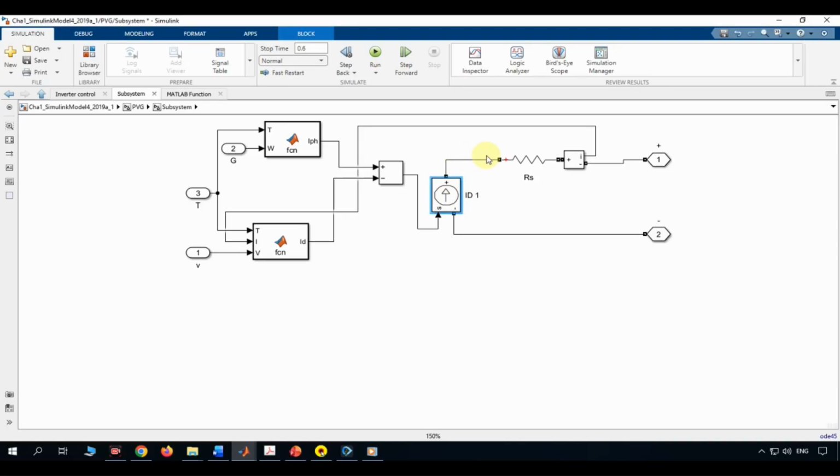It takes your calculated number and turns it into an actual current flowing through the circuit. That current passes through a series resistance, the zigzag, which is the physical resistance term, RS, showing up again here as an actual electrical component causing a voltage drop. And right after that resistor sits a current sensor. It measures the real current flowing through the circuit and feeds it straight back into the ID function as the I input. That feedback loop is the key detail.